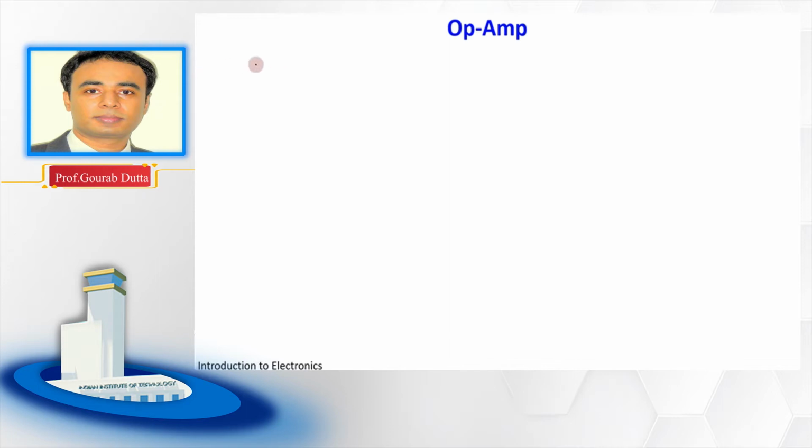So, if you recall, in the last two classes we have discussed a couple of op-amp circuits, and the circuit elements that we have used, which are actually in the exterior of this op-amp, were resistors, right? For example, in the case of the inverting amplifier, we have discussed this circuit. This is the input, which is applied to a resistor R1.